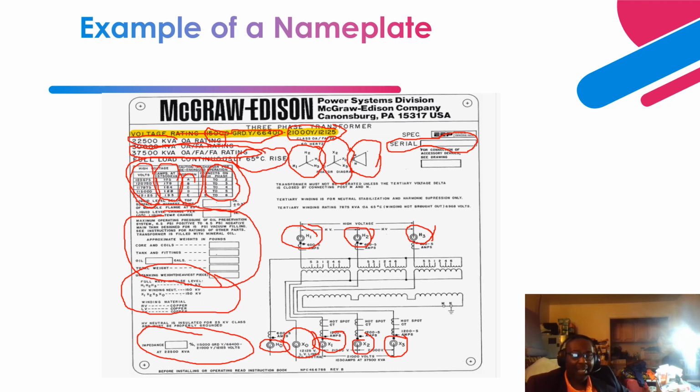So the current that is going through this CT is wired through a winding resistor, a heater, that mimics the heating of the load. And this is basically an adder that is added to the measured temperature of the heater to determine the winding hotspot.